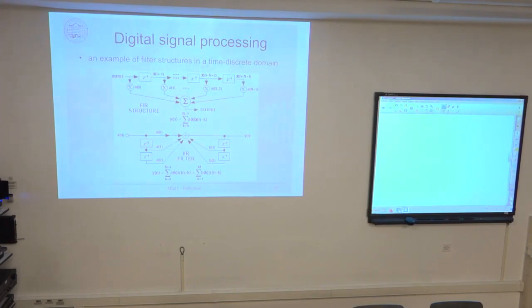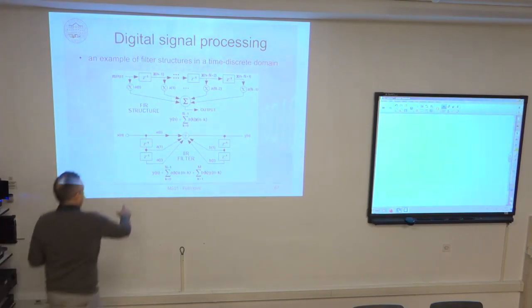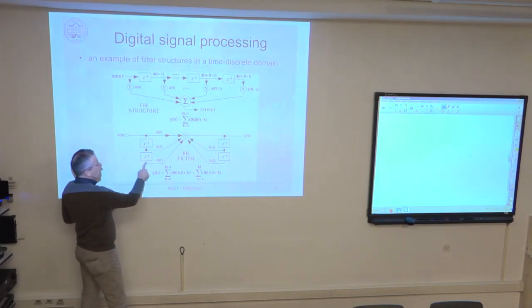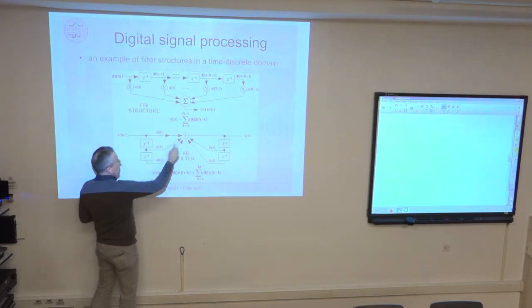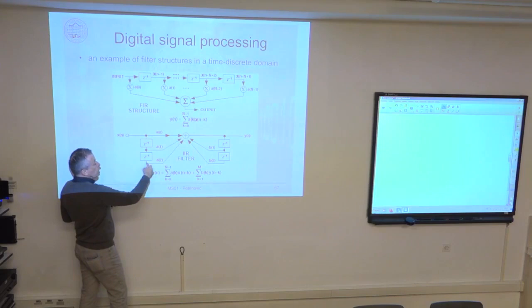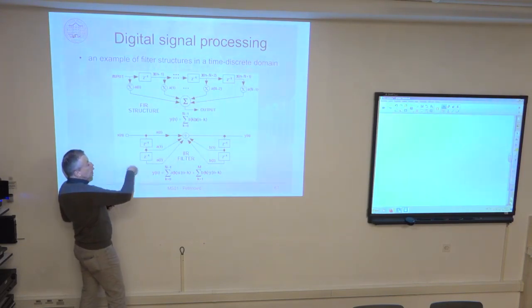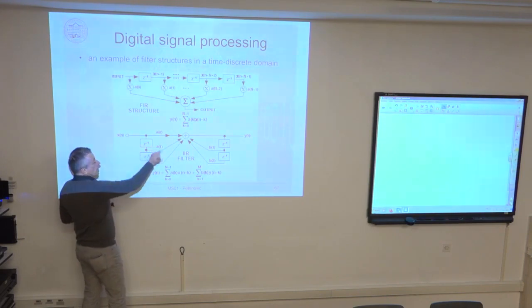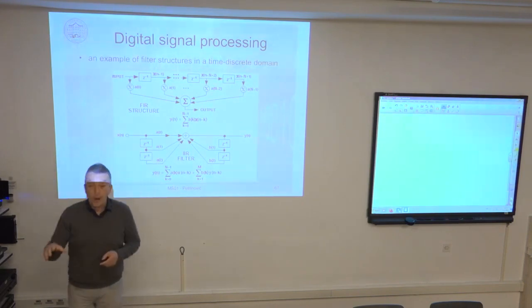For example, this value here is in the X register, and this value is in the Y register. And this pair is used to perform multiplication with addition. But simultaneously, as you do this, you automatically fetch from the memory this value again to the same register X, and this value to the same register Y.